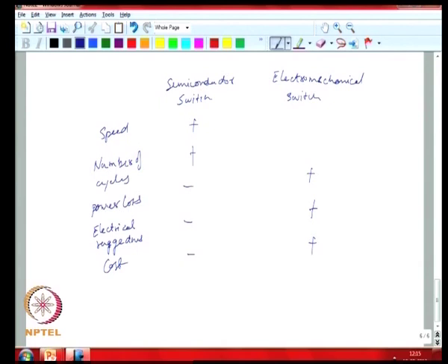So if you look at the peak to nominal current rating of an SCR, it will be much higher than that of an IGBT. Also, in terms of the on state drop, which has an implication for power loss, the on state drop of an SCR is actually lower than that of a typical transistor of similar rating. So an SCR based semiconductor switch is a particular technology that people have looked at for quite a while now. Okay. So if you look at SCR,